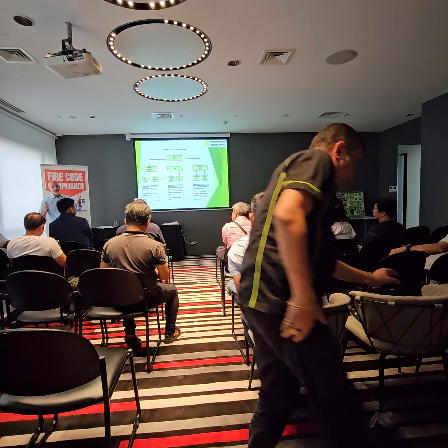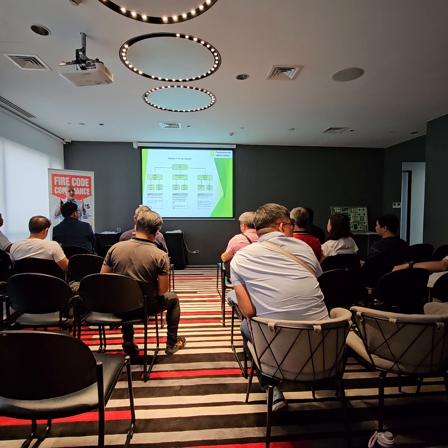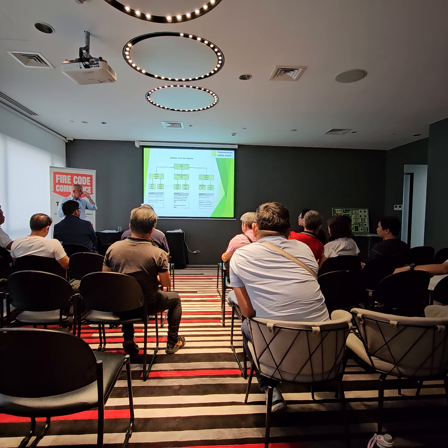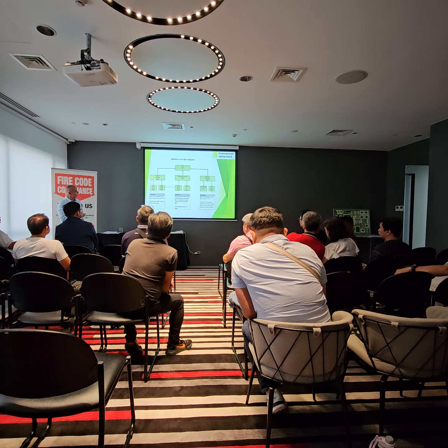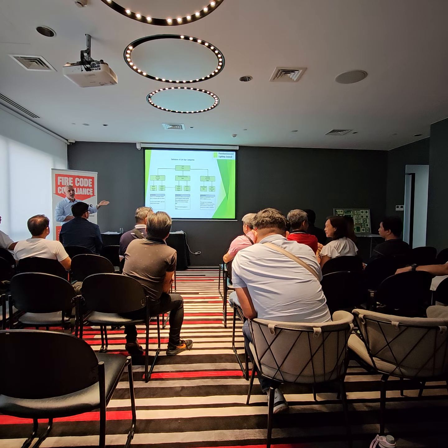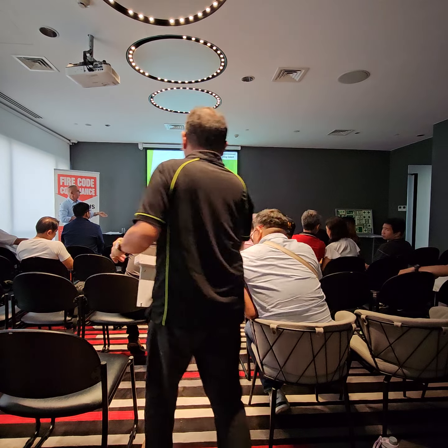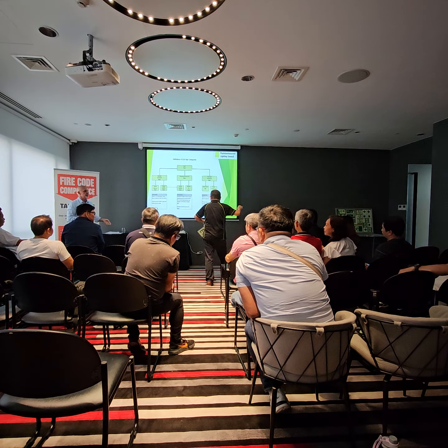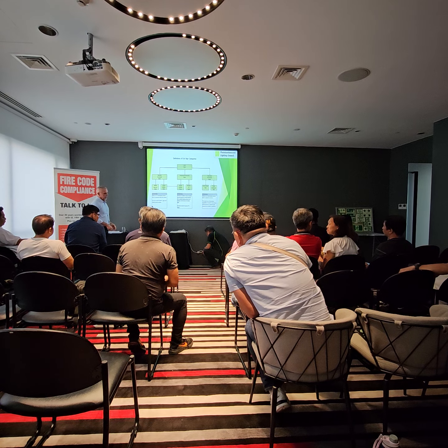What a hybrid is, it has the LEDs built into the sign. So the LEDs run off the mains, and it's sort of like an internally illuminated sign, in that an internally illuminated sign would be charging the batteries. The electricity fails, it uses the batteries. When a hybrid LED sign fails, it uses the photoluminescent panel.